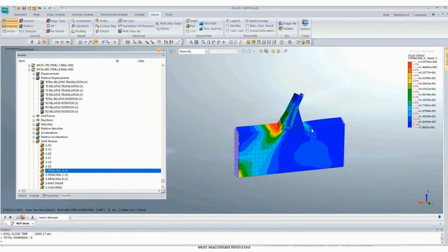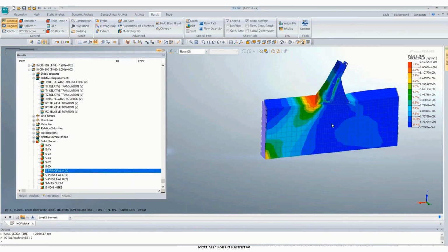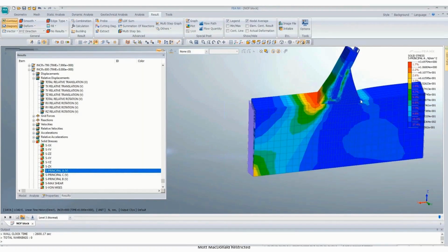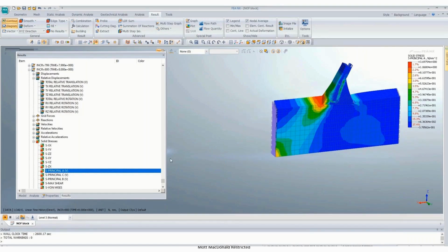After this, let's see how the stresses are varying. You can see the tensile stresses in the range of 3.69, and this is a linear analysis. If it is non-linear, some tension would be there in the base. Okay, let's see the animation first.